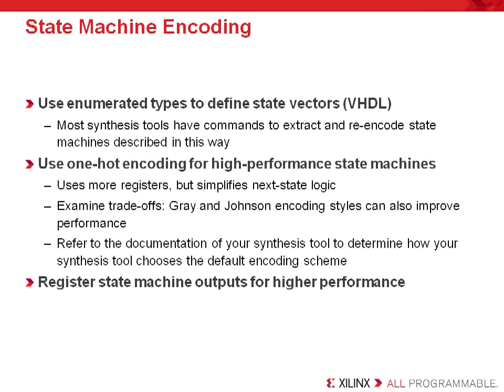This is frequently necessary if you're building a large or complex state machine, since these usually infer extra levels of combinatorial logic. This is why state machines are frequently part of a design's timing critical path. So make sure, after you have separated out the next state logic from the finite state machine outputs, that you also make sure both processes have registered outputs.